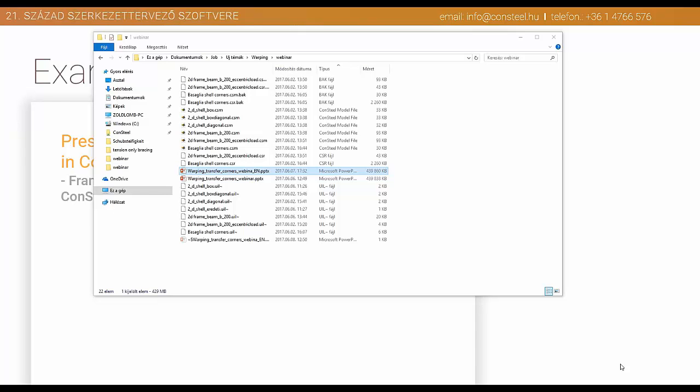Now I made a model portion which includes all the 4 primary members, because I would like to place corners between the columns and the beams. I need to remember that there are certain criteria for where the connection will be placed. Both members connected to each other must be I-sections, the webs must be located in the same plane, and the angle between them must fall within 90 degrees plus or minus 30 degrees.